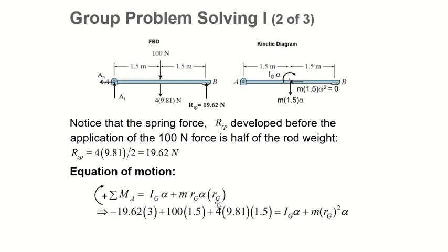So we're going to use the same moment equation, and here is your mass moment of inertia at G and your angular acceleration here. This one again, I'll measure from your G, R distance away, and then of course we're going to put that into there because this mass is that distance away from that axis.